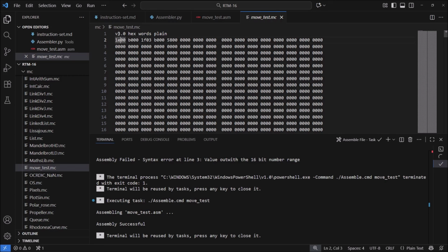And the assembler has done this for us. It's generated this position here and put it in. Now the other one was the 1F, and we're going to be using register R3. And again, the contents are going to come from address B000 back into this register R3. So it's generated the commands correctly, and we've got the end command.